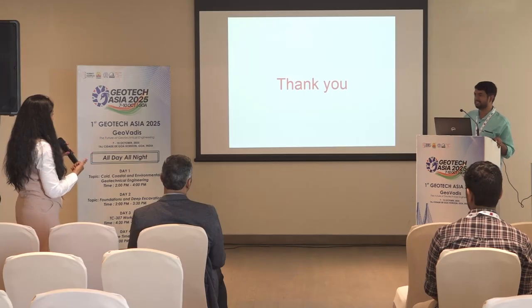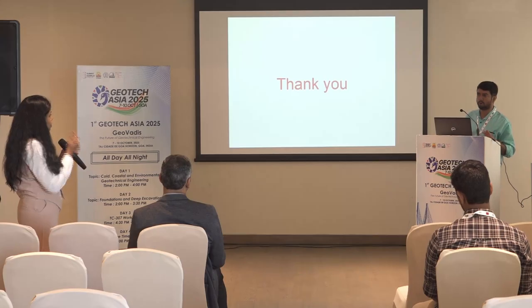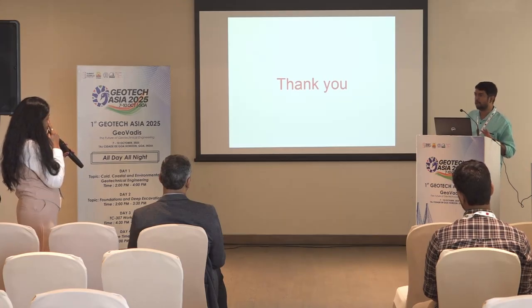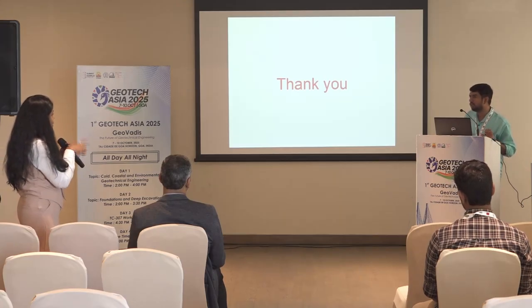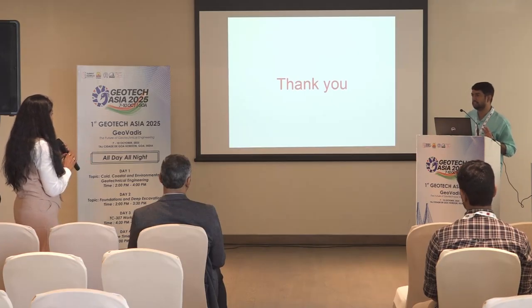1.2 meter. Yes. That may be why I'm not getting any issues if it is properly installed on rock. But I don't think it is, because the settlements are coming only 50-60 mm. In fact, even after reducing the stiffness of the rock to a very low level, I considered poor quality rock also. But still, such settlements are not coming. So we could attribute this entire thing to the pile not being properly embedded in the rock. That's the major issue. Yes.